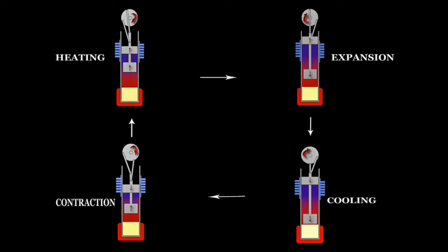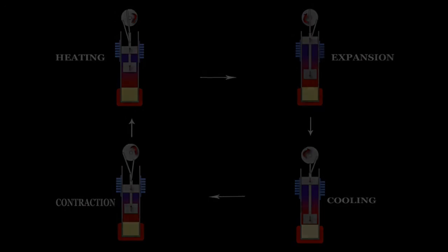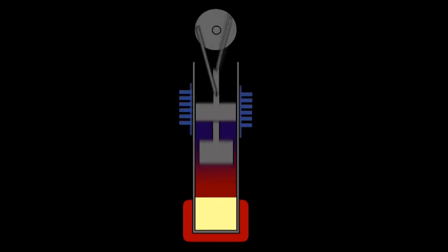At the cooling stage, dry steam loses its heat in the cooler and converts itself into wet steam. At the contraction stage, the wet steam gets contracted. As a result, the power piston moves downwards and so the flywheel rotates. Simultaneously, by the movement of the flywheel, the displacer piston moves upward and replaces the contracted wet steam on the hot oil surface. In all these 4 stages, the same steam recycles itself in the closed operating cylinder and activates the engine.